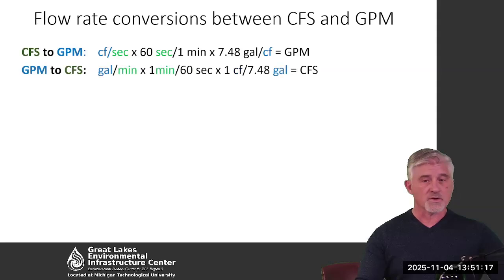Now, if we need to go in the other direction, we're going to start with gallons per minute. We need to get rid of the minutes and get to seconds. And then we have to have our conversion to go from gallons to cubic feet.